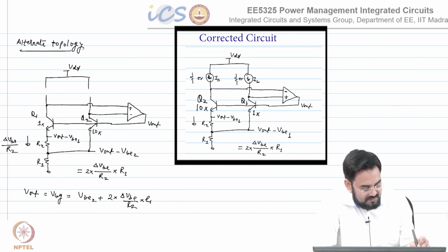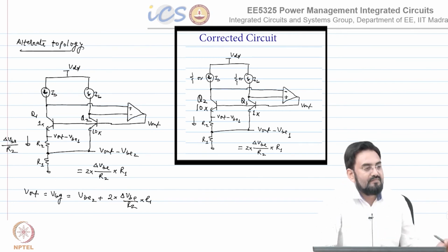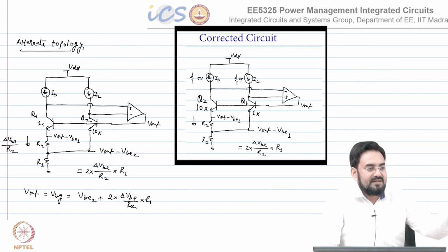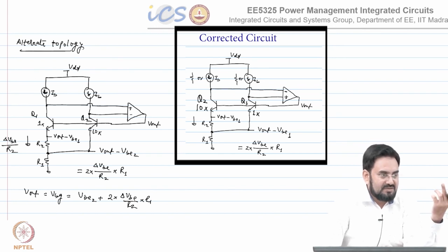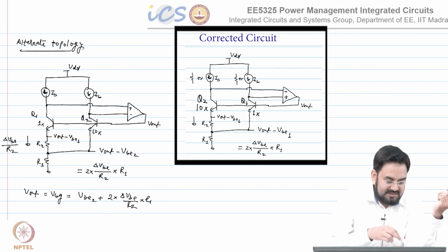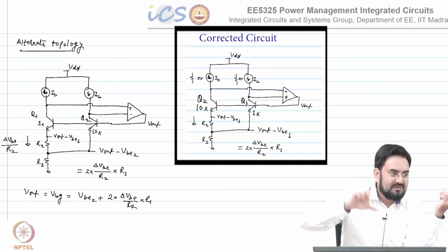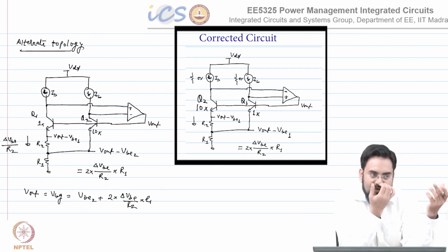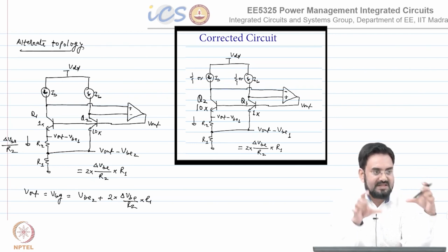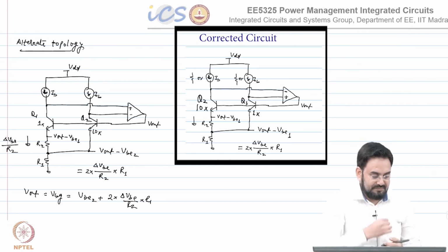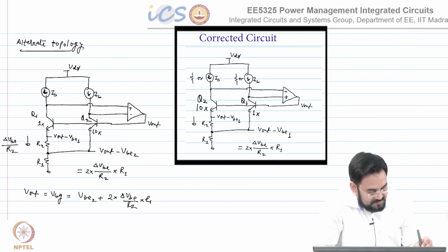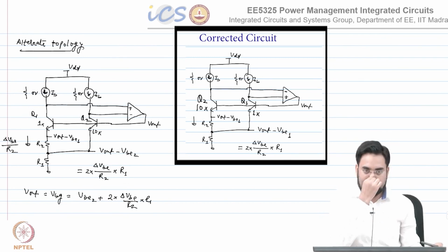So, as long as they are the same. Okay. So, you have a MOSFET in saturation, biased with a fixed current. So, you have a current mirror basically, and since this op amp will ensure that VDS of those two devices are the same, channel length modulation will not affect, and you will always get the exact same current. So, you can use a resistor or a current source.